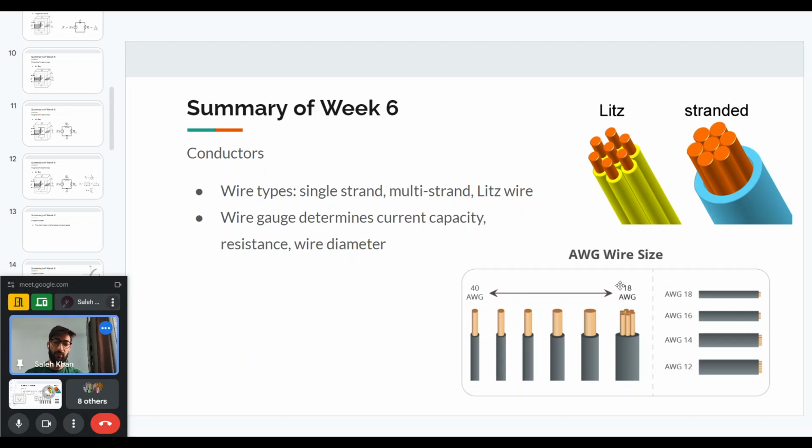The wire will be too large. It will take too much space in the inductor. We will require a very large inductor unnecessarily. So if you want to optimize your design so that the inductor becomes as small as possible, then you can choose the appropriate AWG wire gauge.